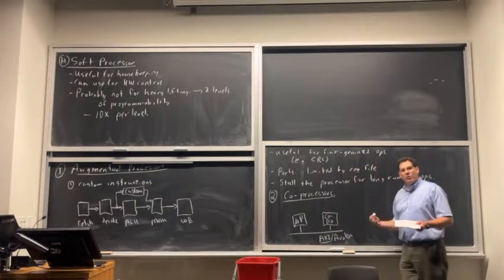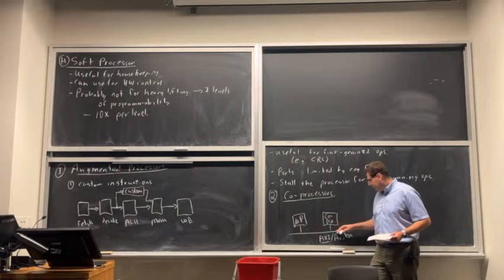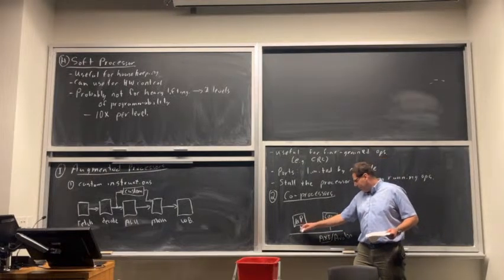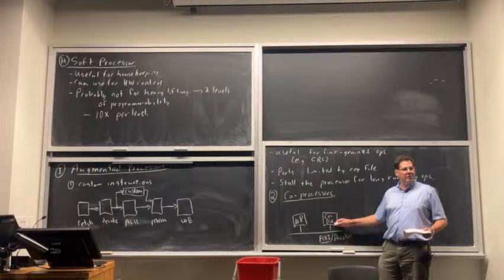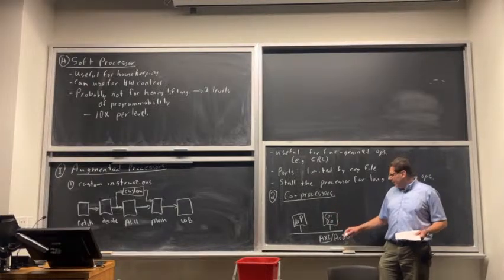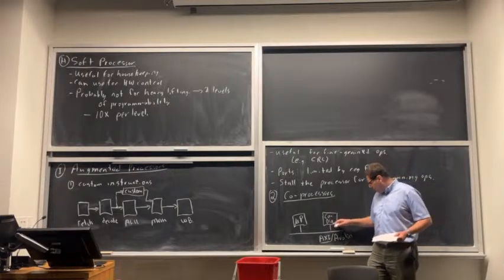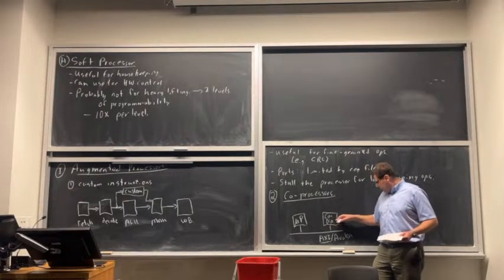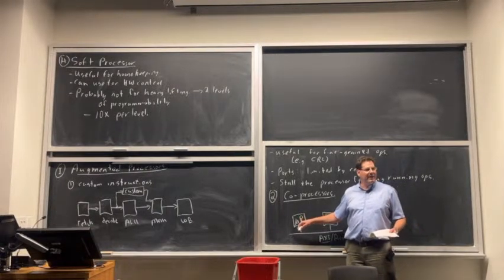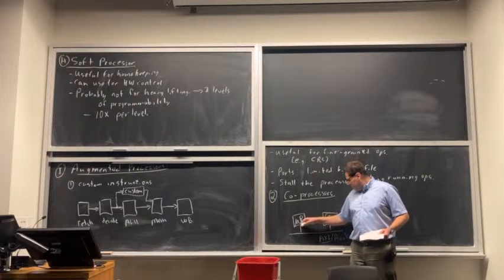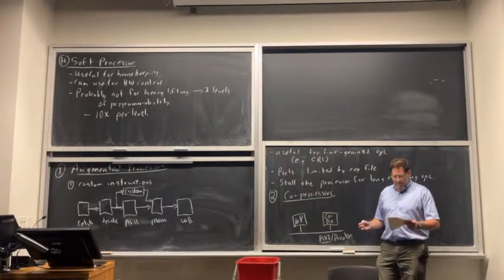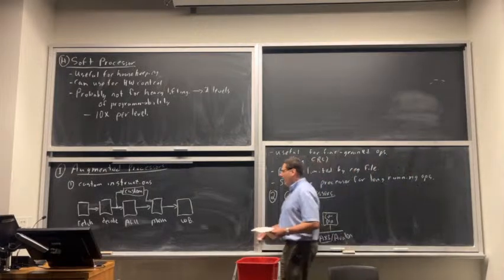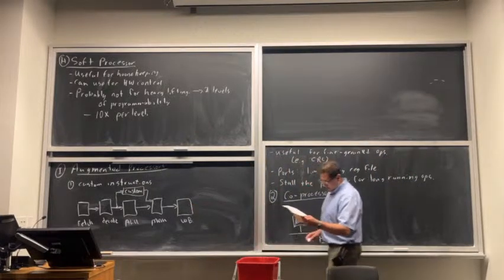So they're not as closely coupled. It will take multiple cycles, for example, for the microprocessor to execute a read and to send something into a register in this coprocessor that might tell it go do something. And it'll take multiple cycles for this coprocessor to say, okay, here's some data that I'm going to write back to you, right? And I want to write it into maybe some registers you have, or write a status register saying I'm done. So the latency is higher than you had here.